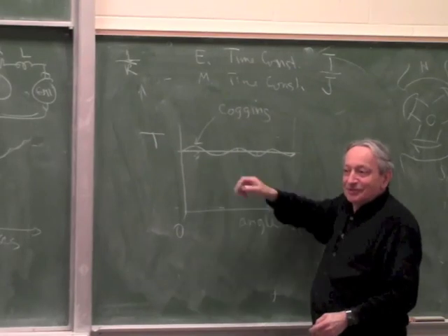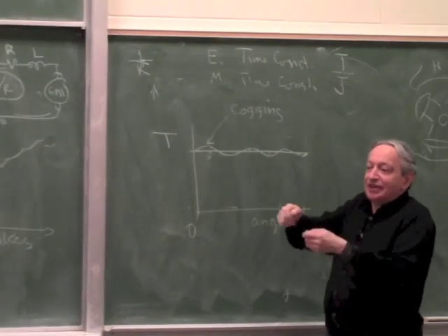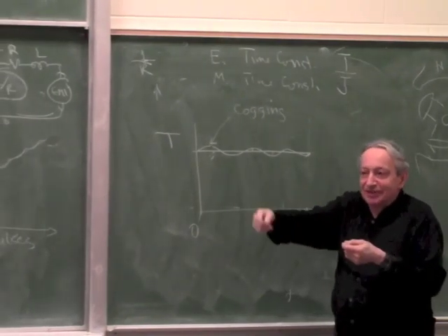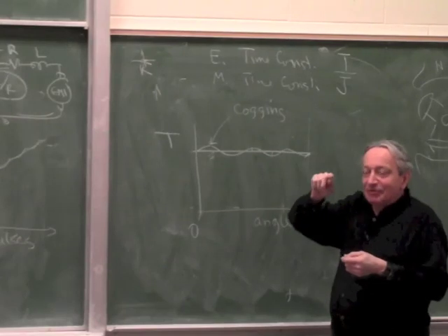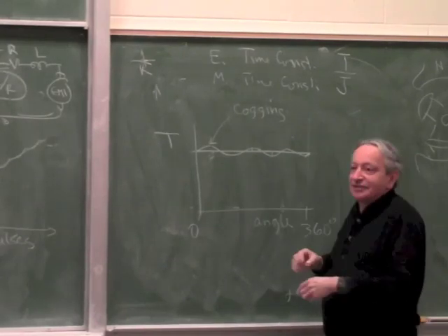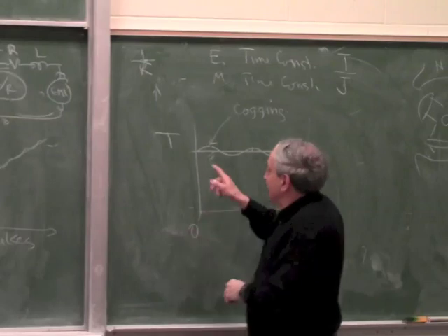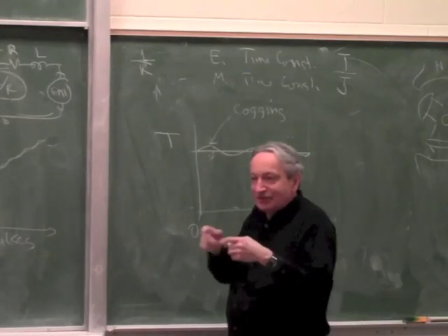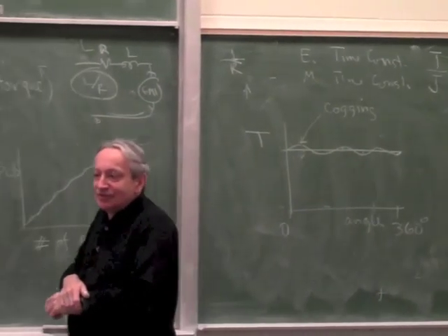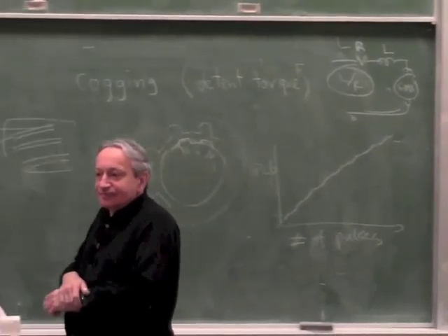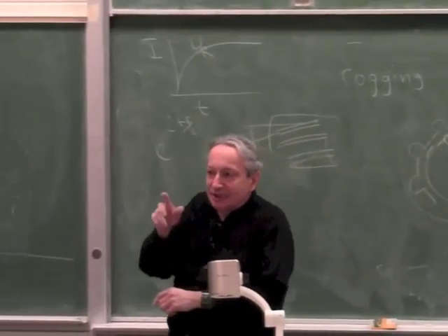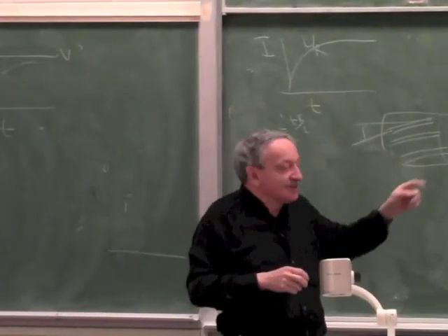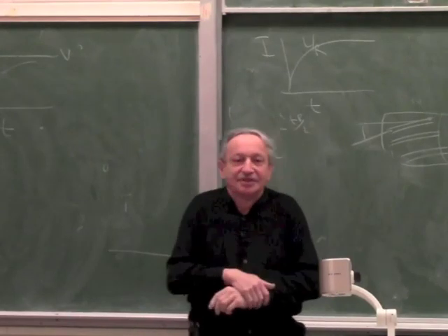So if you have a rubber band attached to the motor trying to wind it up, the speed will fluctuate a bit like this graph. And this happens at a high rate. It's sometimes difficult for the servo to remove that, say if a motor has many poles, and this is quite a high frequency disturbance.